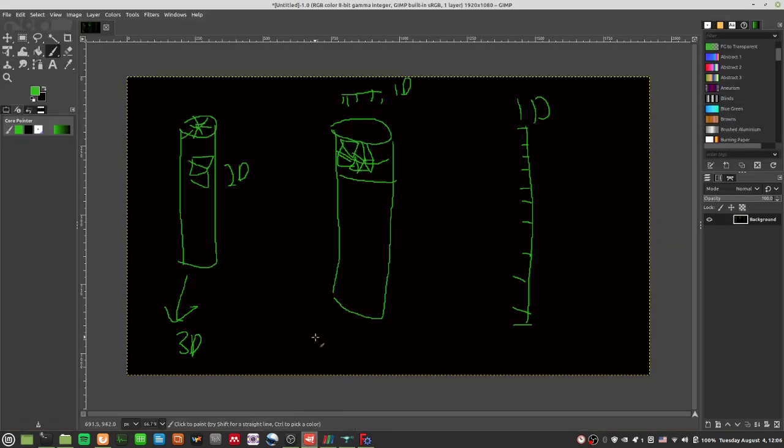So the idea behind mesh generation is, let's say you have a cylinder here, right? Okay, I'll explain all these markings later. So what Salome, Netgen, or even Gmsh will try to do is they will section this cylinder in terms of length by 1D elements. So in this direction, they will try to cut it up and discretize it. And that's how they generate the 1D mesh. Maybe they do it for this side as well.